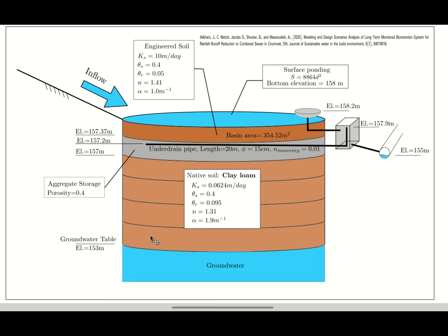Now keep in mind that you can discretize it any way you want. You can discretize it using a finer grid or a rougher one. Of course, the finer it gets, the more accurately infiltration is modeled, but then the computational costs will go up. But for this particular case, we may not really care as much about how accurately we are modeling infiltration, percolation into the soil, or recharging the groundwater.